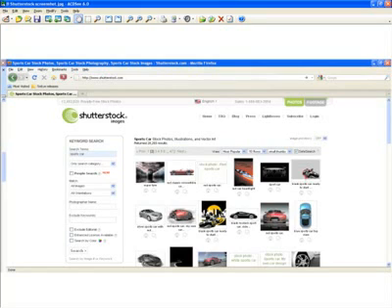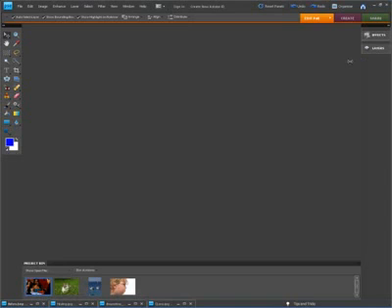Low-res graphics tend to produce very poor quality, and that is going to be the case if you end up using a low-res graphic. For example, if you have a 1-inch by 1-inch engraved object, the resolution of that object needs to be approximately half a megapixel. As you go up to, say, a 4 by 6 inch engraving, you need to be approximately 2 megapixels, all the way up to about 12 by 12, where you need to be right around 8 megapixels. So the higher the resolution of your graphic, the better the overall graphic quality output is going to be.